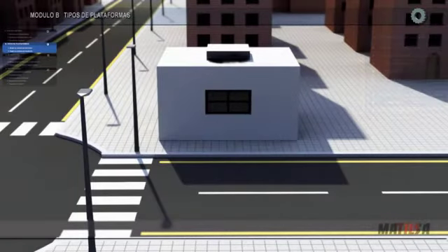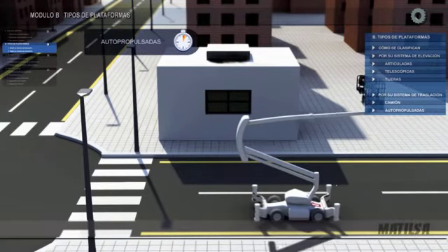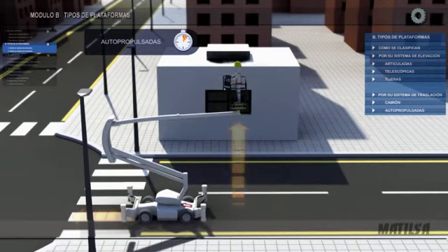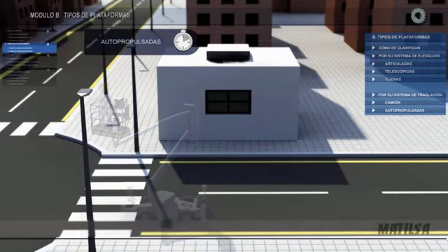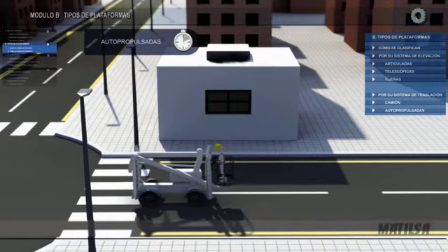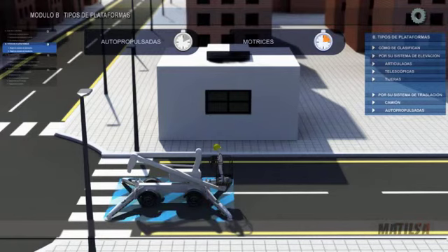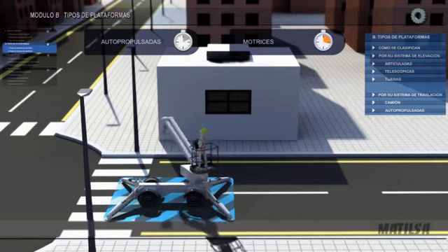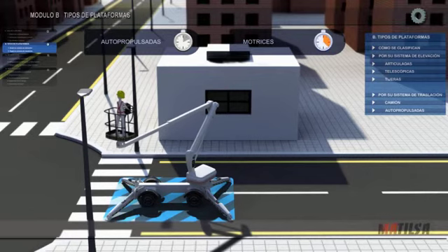Self-propelled platforms. Self-propelled platforms are those that are able to be transported with the arms up and the operator controlling it from inside the basket. There are other platforms on the market which do not allow for transport while in the raised position. These machines are called motorized machines. They weigh less and therefore, depending on the height at which they are to be used, need stabilizers to increase the base area of the machine. The time needed to elevate this type of machine is greater than with the self-propelled ones.